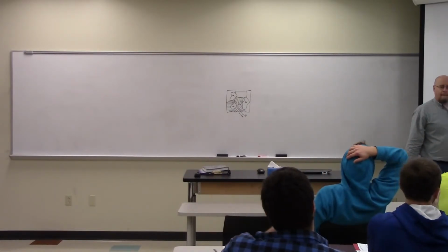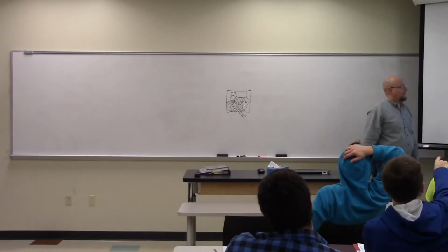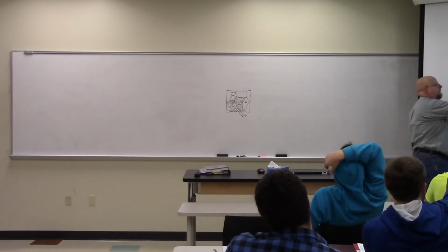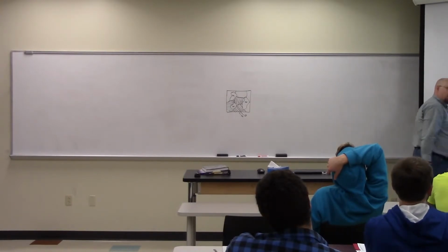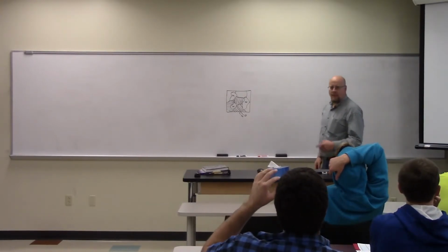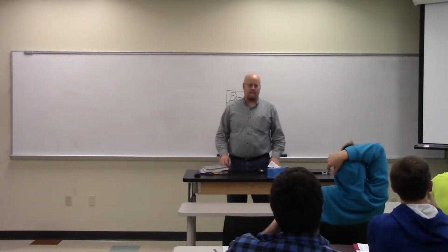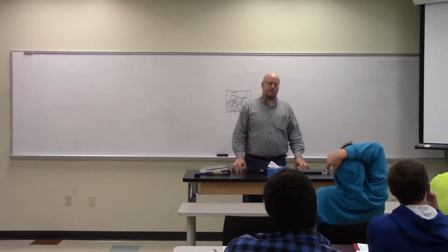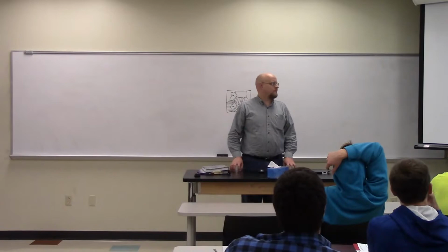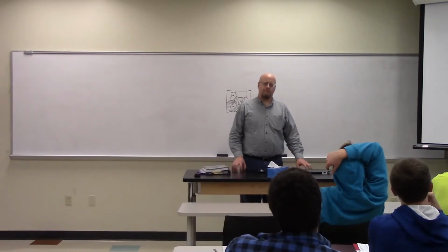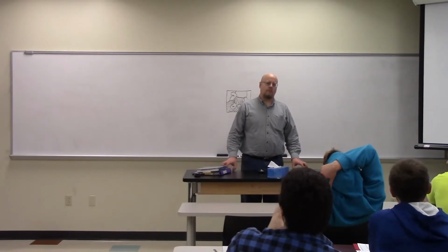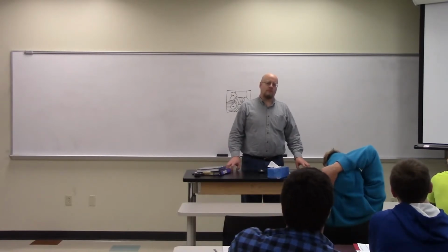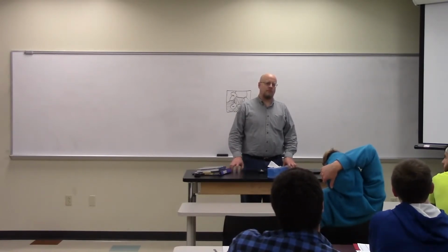Okay. So if we did that same thing where we went to like 50% fine pearlite, and then we just went straight down, the rest would be martensite? Yep. So is there an exact transition point from coarse pearlite to fine pearlite to bainite? Nope. Okay, so if it's in that middle-ish area, it's just somewhere in between coarse and fine pearlite. What's that?